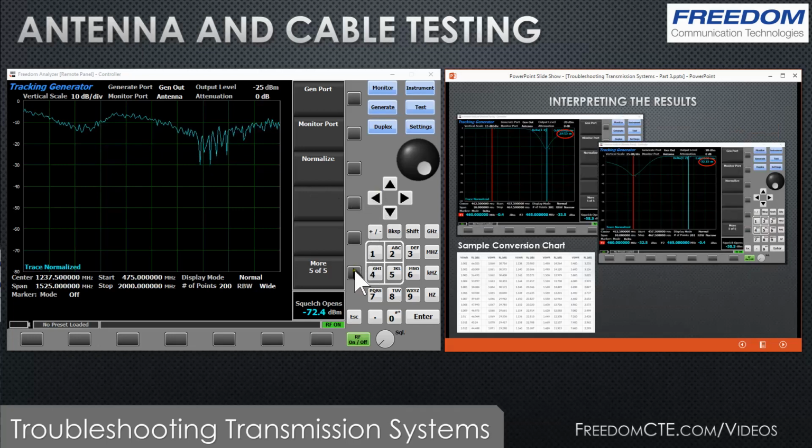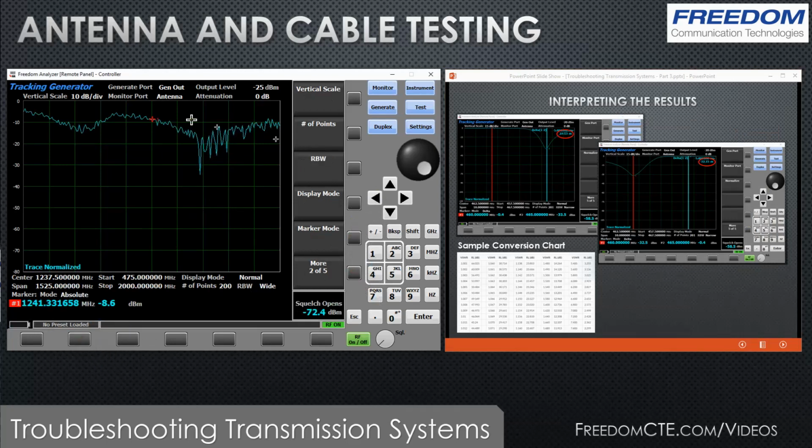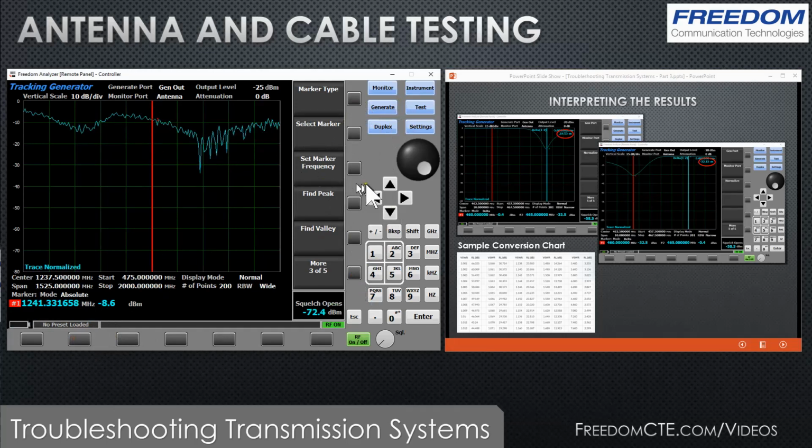So first of all, let's turn on a marker. Come here to marker mode, select absolute. You can see the marker here. I'm going to change the marker style or type to a vertical bar, to make it easier for us all to see. And I'm going to move this marker over here towards this relative low, and you can see this relative low is somewhere in the low 800 megahertz,